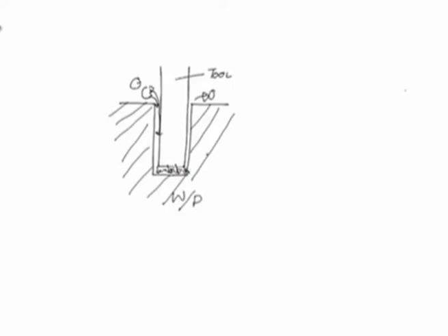Therefore, this is an inherent limitation of this process, where very high aspect ratio holes cannot be drilled in an efficient manner. Under ideal conditions, penetration rates of 5 millimeter per minute can be obtained.